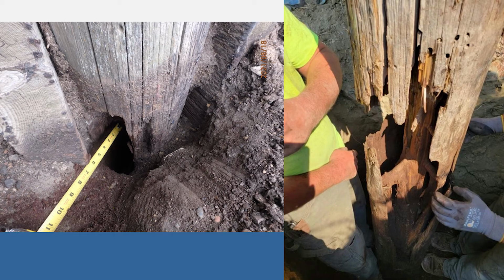And you do have to be cognizant of the angle that you're actually drilling into the pile, because that affects your area calculations, stuff like that. Both of these voids were discovered underground, so you can see the ground line there on the pile, and the voids are underneath that, and the measurements were taken just above that though, so it's really easy to miss stuff that might be buried.